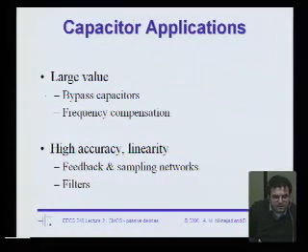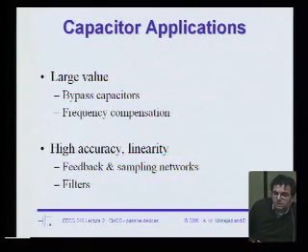You put them outside like a factory that has lots of, let's say you have a factory with lots of motors, lots of inductance there. So if you don't have that capacitor, the angle of your load is actually going to be really bad for the power supply company. They have to supply inductive power to you, and they're going to lose money. So they actually will require you to put a bypass cap on site to compensate for your load angle. We need them on chip too.